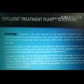Wastewater screening is for the most part grouped into either coarse screening or fine screening. Screens may be manually or mechanically cleaned, with only older and small treatment facilities using manually cleaned screens as their primary or only screening device. Coarse screens are normally used as primary protection devices and more often than not have openings of 10 mm or larger.